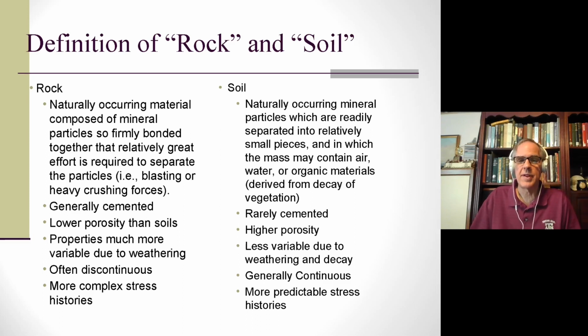You do see them some with clays, higher porosity, less variable due to weathering and decay. They're usually continuous. You don't have the large cracks and fissures, generally speaking, unless you're talking about certain types of clays, as you do with rocks. And they have more predictable stress histories. Rocks, just as an aside, generally tend to have greater strength than their soil counterparts.